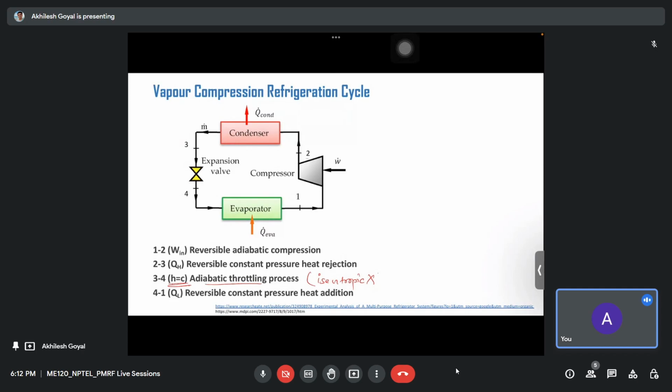That question may arise, but in the case of refrigeration system, even if we put the cylinder piston arrangement, the work obtained is very less, because it is going from liquid to vapor, and the pressures are not as high as in the case of power cycles. So the work obtained in that case will be very less, and that will not justify the cost and the bulky structure of this cylinder piston arrangement.